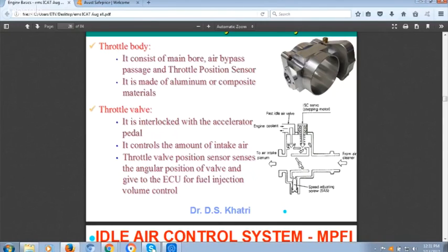Now, you have gone to Leh or any cold place. This throttle will remain the same. You are not changing this throttle. But there, because it is very cold, you have to inject slightly more fuel quantity, and you also have to increase the air slightly. And now by foot you cannot do that. It means there should be some mechanism which changes the quantity of air as well as fuel. Fuel you can change by changing the duration of injection. With that, you can have a lookup table. But how to do this?